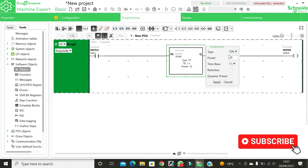There is preset. This is where you set the amount of time. Then I can say 5 seconds. Then for the time base, this is where you set whether you want your time to be in minutes, in milliseconds, and so on. For retentive and dynamic preset, we shall leave it at that. Then we can say apply.